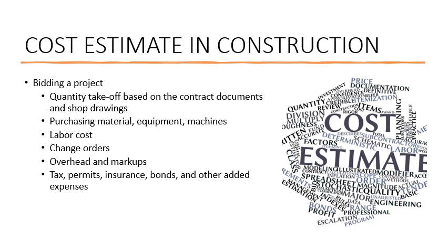And typically, we start estimation with quantity takeoff after we receive the contract documents and maybe after we draft our own shop drawings. We start doing the quantity takeoff, and then with the unit prices, our own data sources, we do the cost estimation. And typically, it includes purchasing materials, equipment, machines, and also labor costs.